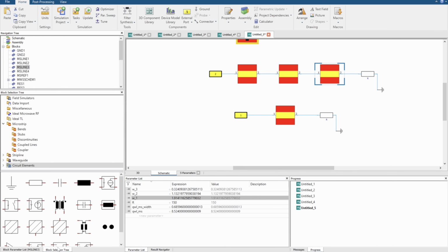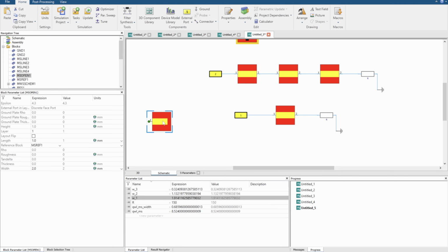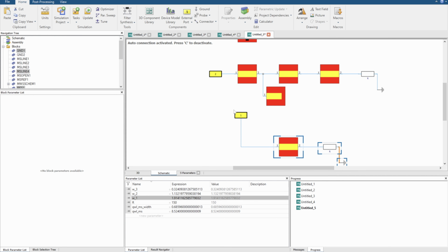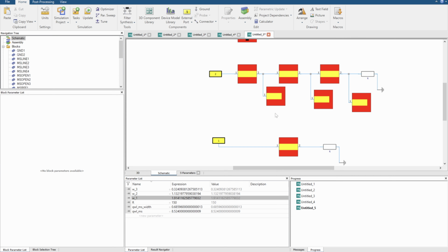So we're just exploring, remember, microstrip blocks. Let's go through. So we've also got stub blocks we can play with. If I was just creating a network, I could add a couple of stubs in here if I wanted to. Let's move this down. And I could say, you know what, my matching network, you can have 3 stubs as well. Sure. And you could do the exact same process. You have 6 parameters to play with. Good luck, optimizer. Can you achieve an impedance match? So that's what it's also capable of.